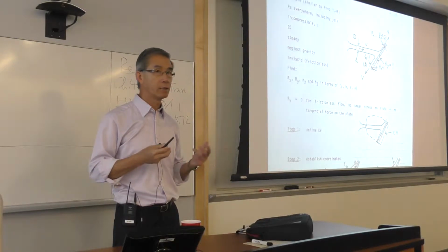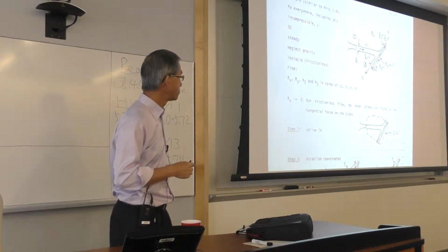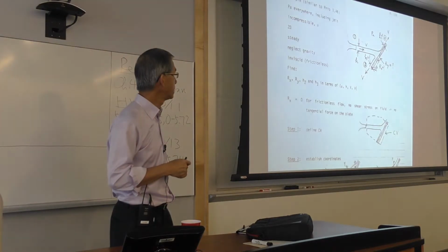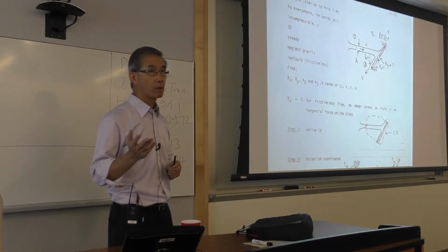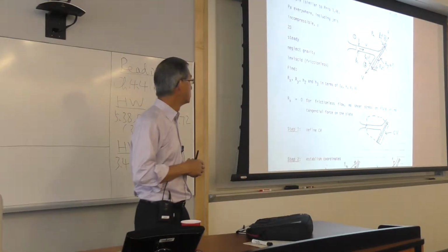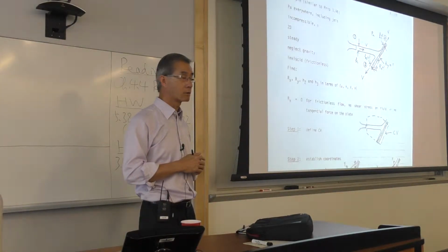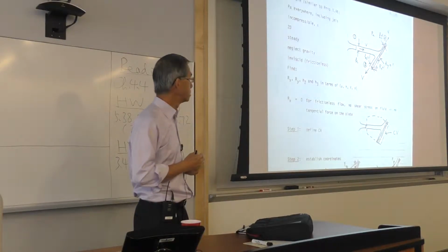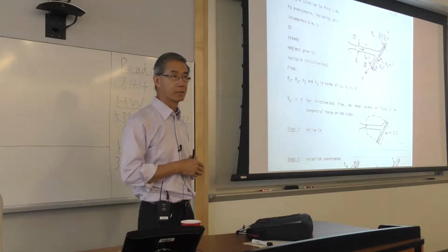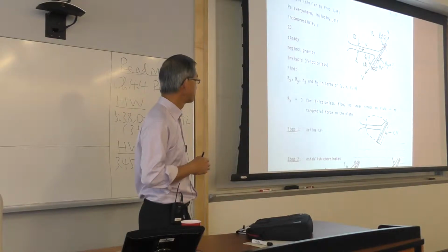It's an open jet, it's atmospheric everywhere. And that's a condition we have used many times. Steady problem, so no unsteady term. You can neglect gravity, so if it's water, the weight of the water is inconsequential. No friction, inviscid, frictionless. Shear stress is zero.